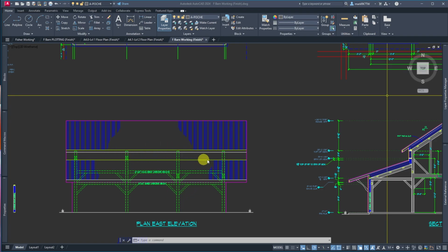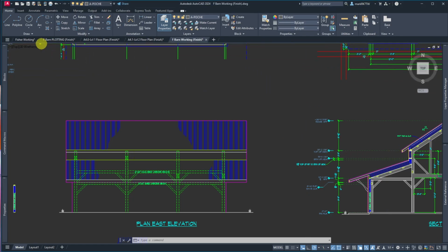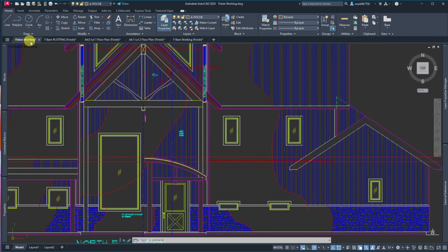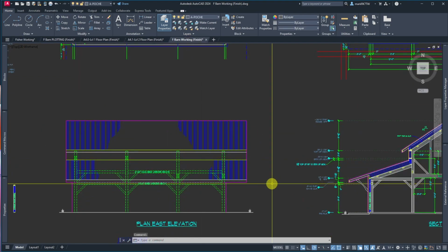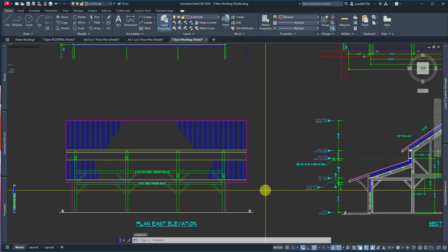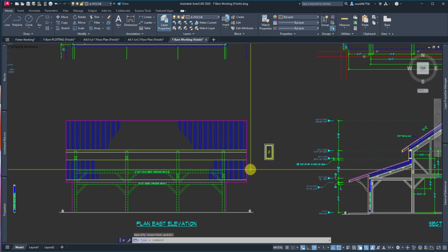We're going to take a shot at what goes in these clerestory windows up here. And one of the things I'm going to do is go to their house and steal one of these windows. I don't think I've got enough room in the clerestory. We'll grab one. So let's grab that one. Oh, okay, it's got trim. We're just going to grab that one. That'll be enough. Control-Shift-C. I'll come right to the middle of it, come over to my working drawing, and then I will Control-V and drop it. And you'll see how handy that'll come in.